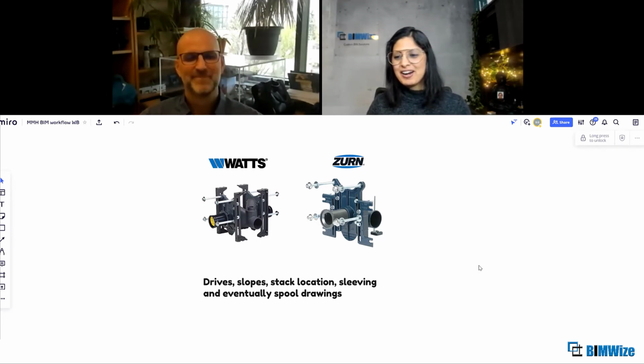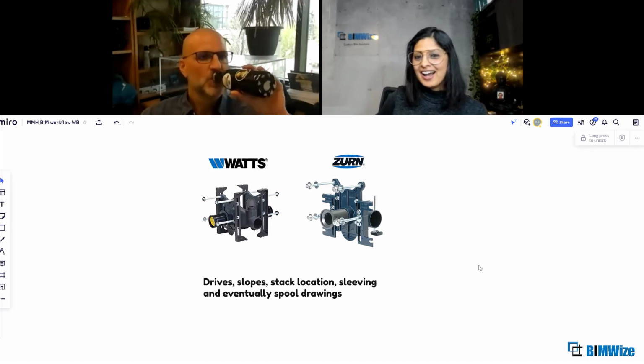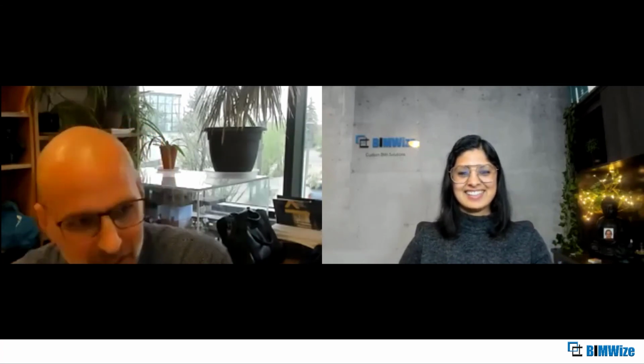I'm going to move to our next section, which is the impossible questionnaire. So the first question: what is the acceptable slope for an interior ramp that is not located in a barrier-free path of travel in a restaurant? Well, that's a long one. I'm going to say 6%. The answer I have in front of me is 1 in 10. So that's 10%. 10%, yeah. Quite a lot steeper, actually.